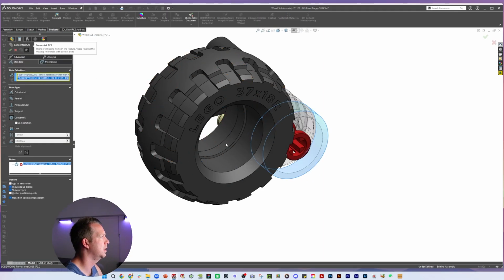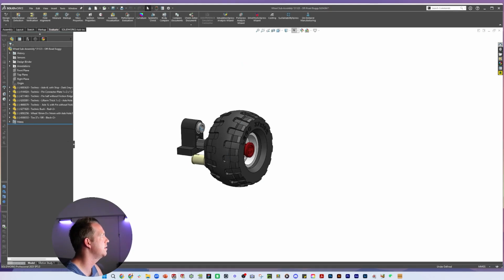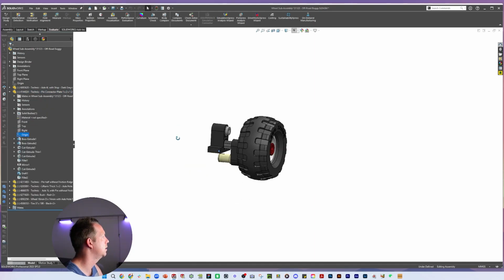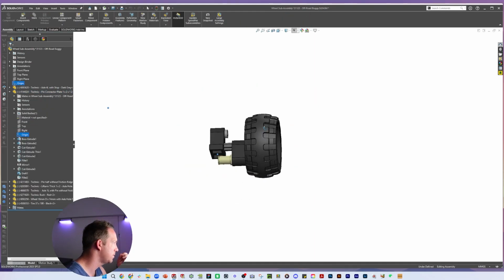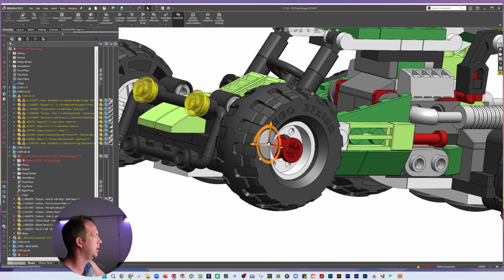These two, missing a face to mate that round one. Now, there's no errors here, but it's underdefined, and I don't really like that. So let's take this part and use it to mate. Is this the best way to do it? Probably not, because these are referencing different parts. Now we're getting a few errors.